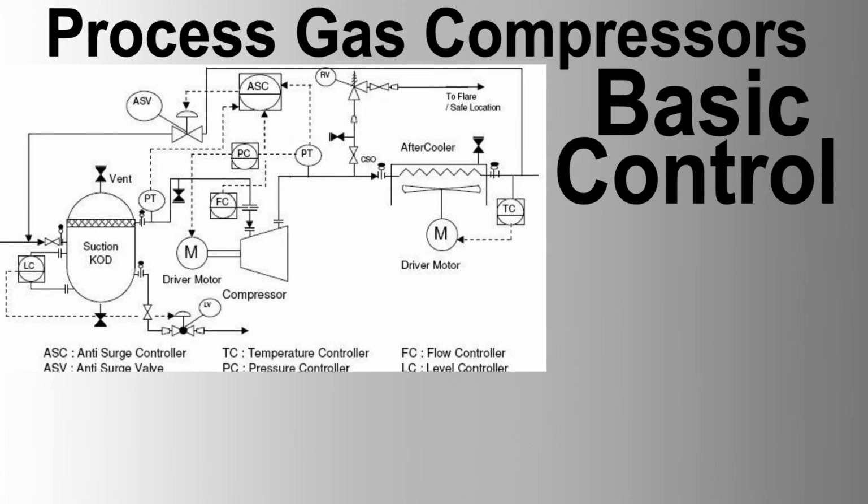Step 5. Commission the new compressor and monitor performance. Gradually bring the new compressor online and monitor its performance. Adjust control parameters as needed to ensure stable and efficient operation. By following these modifications and considering the impact on control strategies and loop configurations, a process or instrument engineer can successfully integrate a new compressor into an existing system, ensuring efficient load sharing and reliable operation.